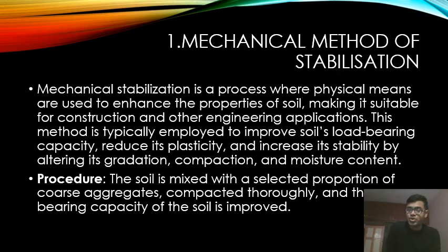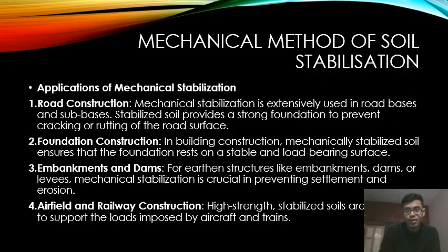The procedure is this: the soil is mixed with a selected proportion of coarse aggregate, compacted thoroughly, and then the bearing capacity of the soil is improved. This is the mechanical method of stabilization. As for applications, we can use the mechanical stabilization method in road construction.